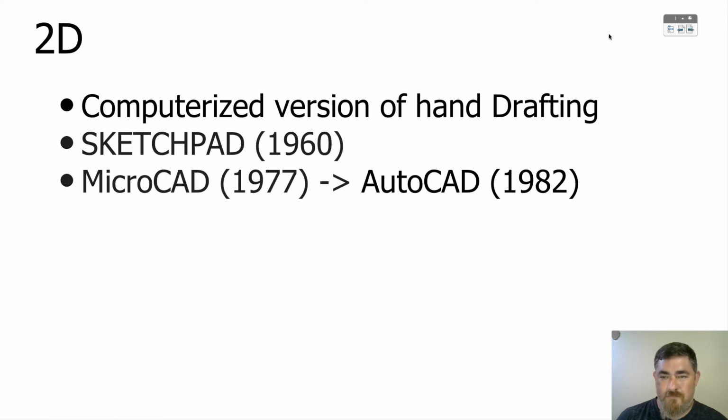So let's go. 2D CAD is basically just doing hand drafting on the computer. So you're telling the computer, draw a line here, trim this, and you tell it exactly how big to be as you're drawing it. You can always move things around and copy things. But when you draw the geometry and you move it, you're setting the size of it. And then you can add dimensions to measure what's drawn, just like it was by hand, but it's a lot more precise.